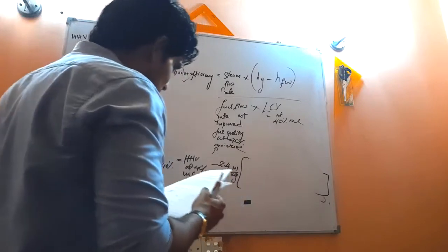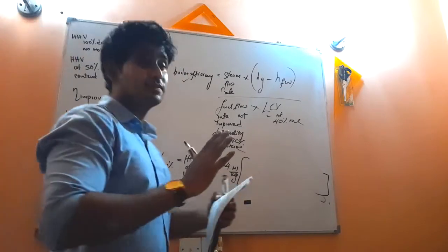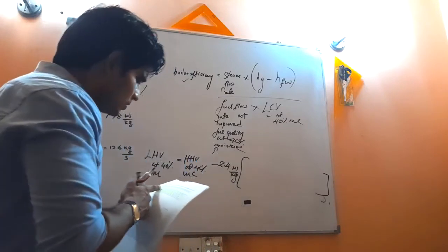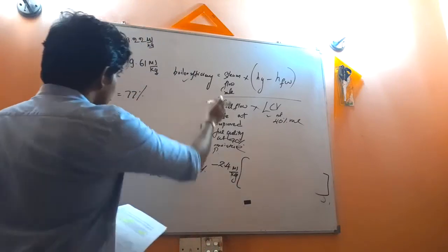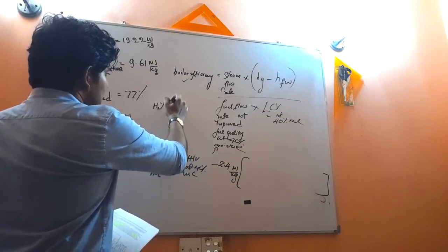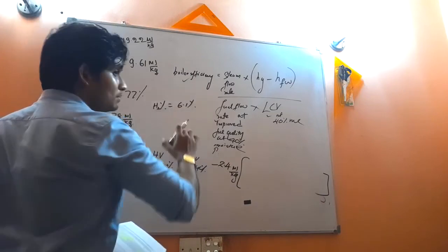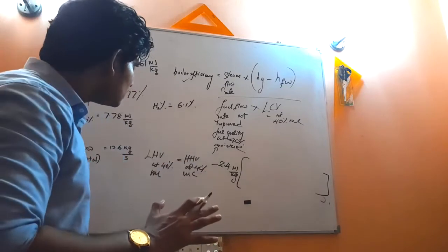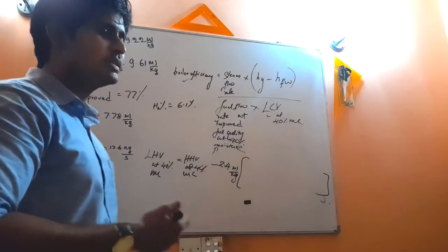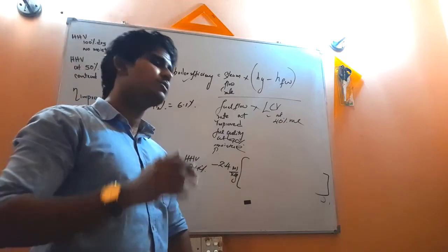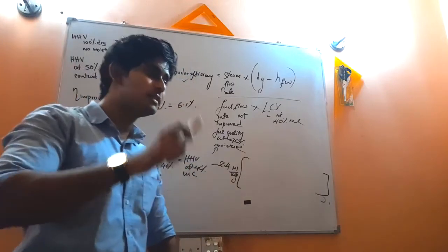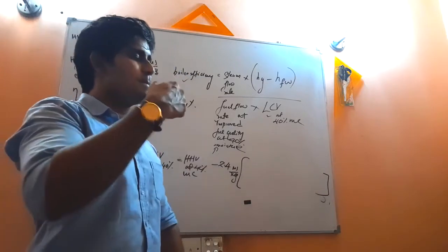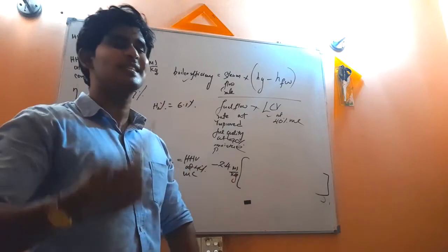There is a fuel profile when the fuel is 100% dry, because the fuel profile is defined according to that. So the hydrogen percentage, you know what it is? That is 6.1%, but when the fuel is 100% dry. Now if the moisture percentage is 40%, that means 60% of pure fuel is there, which means 0.6.